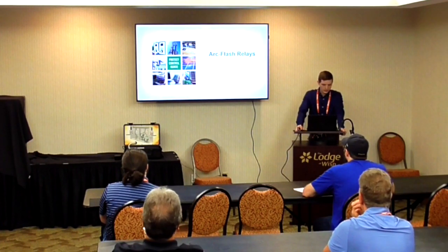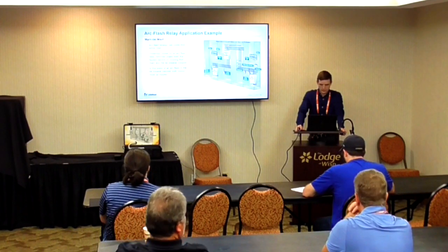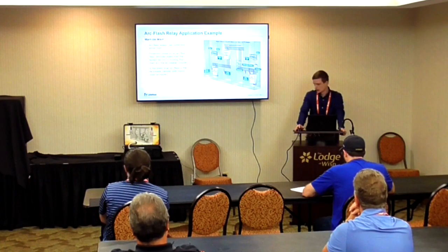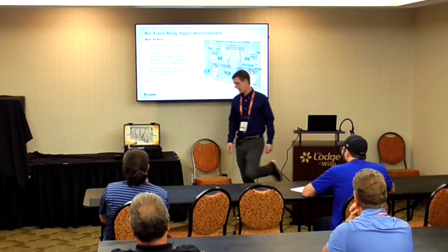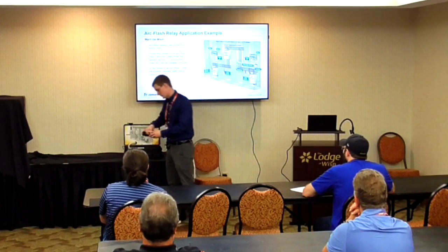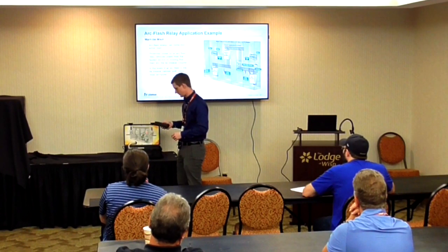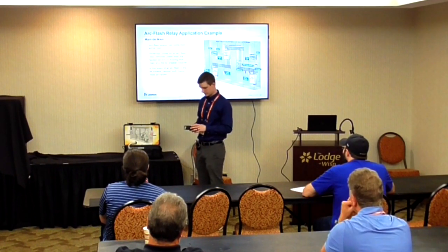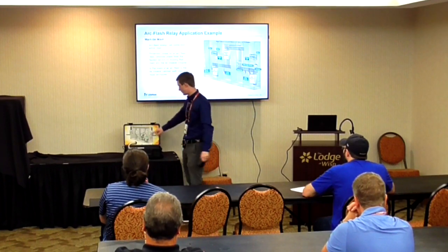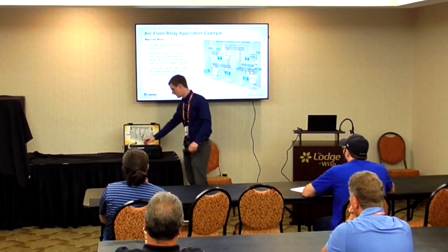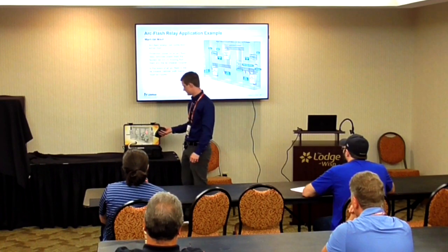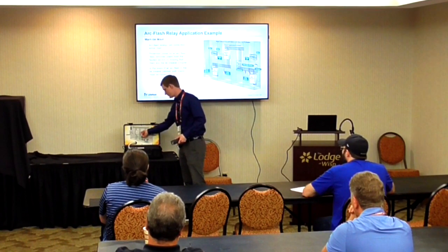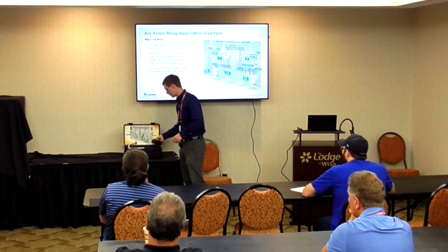I'm actually going to cover the arc flash relays in a little bit more specific, since that's what we at Littelfuse specialize in, and we'll cover some different configurations. Real quick, I'll just show you exactly what happens in the event of an arc. So let this thing charge up for a second. This is going to be a bit like a neuralyzer from Men in Black, so don't look directly at it. But you'll see here that you've got your point sensors, and then you've got your breakers, and the relay is down in here. And that opens as soon as the light is detected on the point sensor.